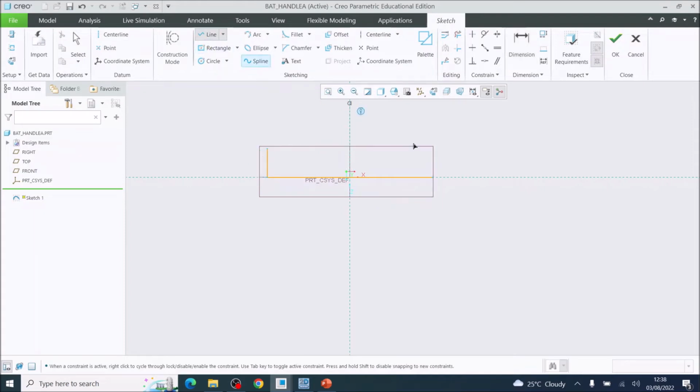I'm going to come across to the other side, and I'm going to draw a vertical line, making sure that it's not the same size. As you can see here, the other line goes green, so slightly smaller. Click OK. Disconnect with the scroll wheel button. Choose the dimension tool, and I'm going to set that at 12.5 in length.